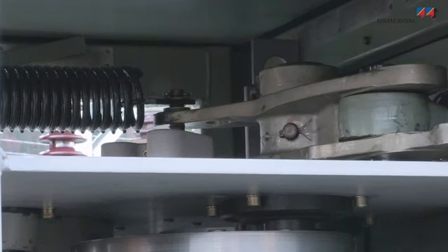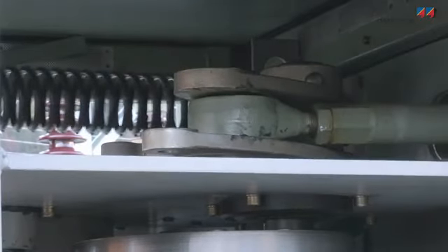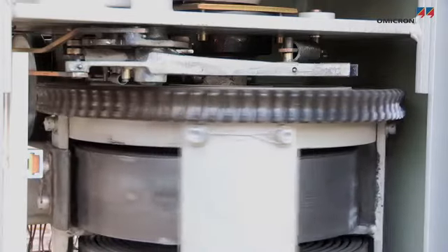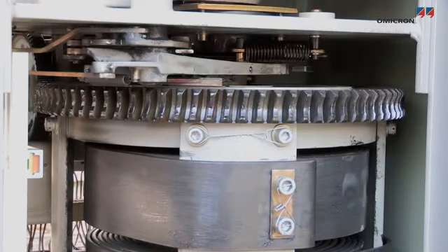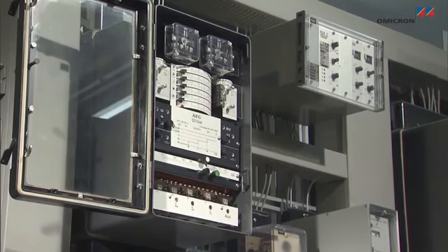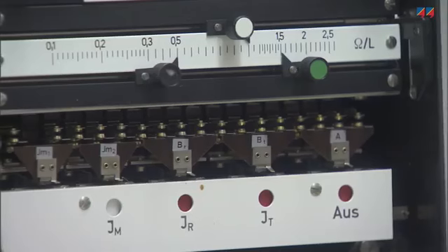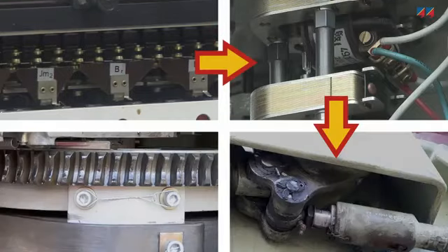The breaking element is usually operated mechanically by a stored energy system. The energy that opens and closes the contacts is typically stored in a spring, hydraulic, or pneumatic device or system. The stored energy is released by the trip or the close command signal. The command signal activates the trip and close coils, releasing the drive mechanism to perform the opening and closing operation.